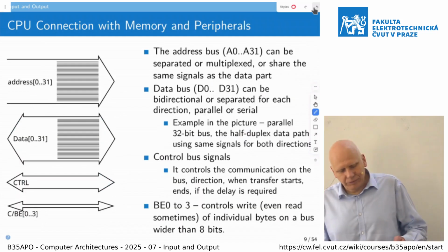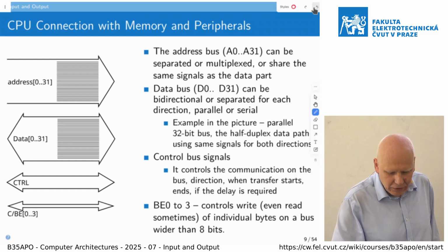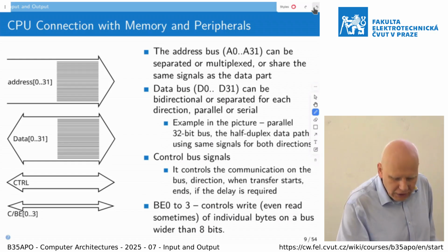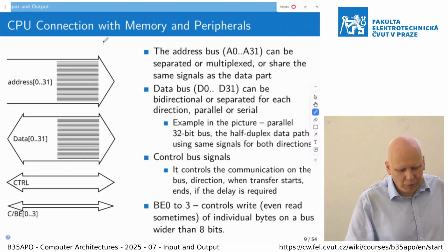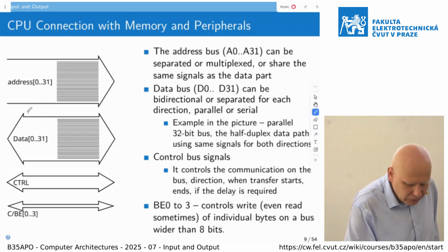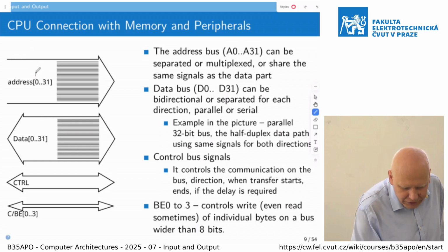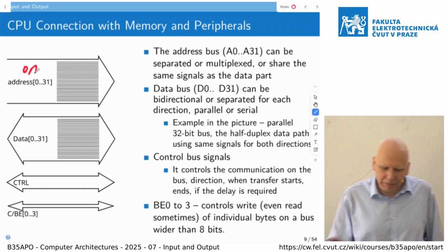Those interfaces, usually for the simple parallel bus, consist of some set of signals. So for example, for a 32-bit computer, we can have typically connected peripherals in 32-bit address space. There are some problems that usually we have even a 32-bit or 16-bit data bus, so least significant bits of the address bus, 0 and 1, for example, are not used directly, but we can skip that.